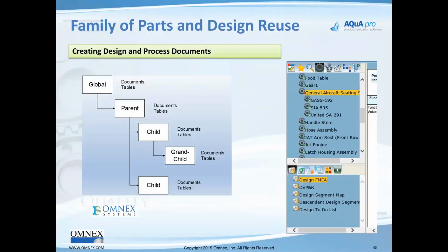The real use is going to be in what we call design reuse. Folks, creating these documents takes a long, long amount of time, and really having that baseline that we talked about, and then using that baseline. So a design FMEA is not a standalone. A design FMEA links to a DVP&R or a test plan. You identify special characteristics, and you have the process flow, PFMEA, and control plan. That's a lot of work that's being done.